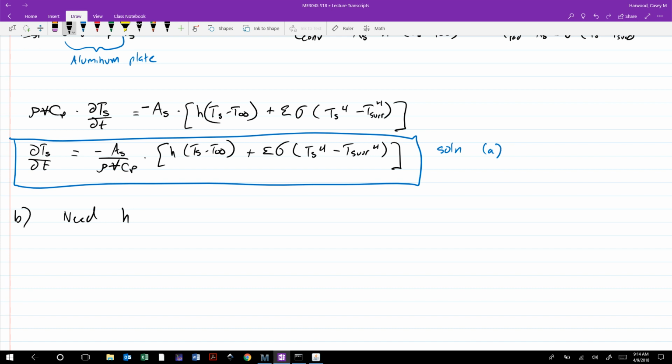The whole plate, right? We're considering the net heat loss from the entire plate. We're not putting a temperature probe on it and just trying to figure out the heat loss from one particular location. So if in doubt, zoom out and look at the problem and say, am I considering heat loss from the entirety of an object? If so, we're dealing with average convection coefficients. It's very specific times when you'll be looking for local convection coefficients, and I'll try to make that clear when we're doing that. So the h we're looking for here is really h bar.